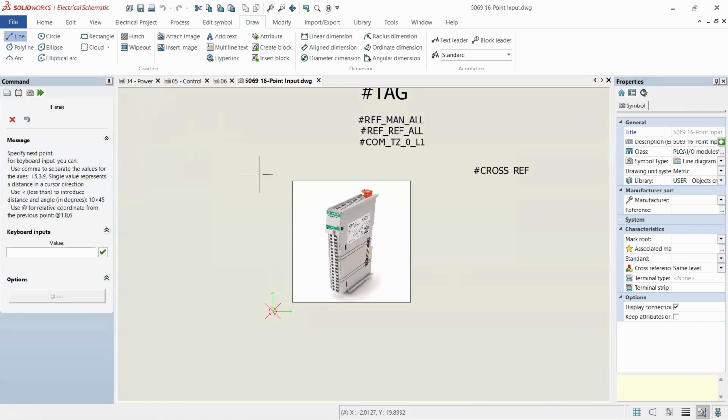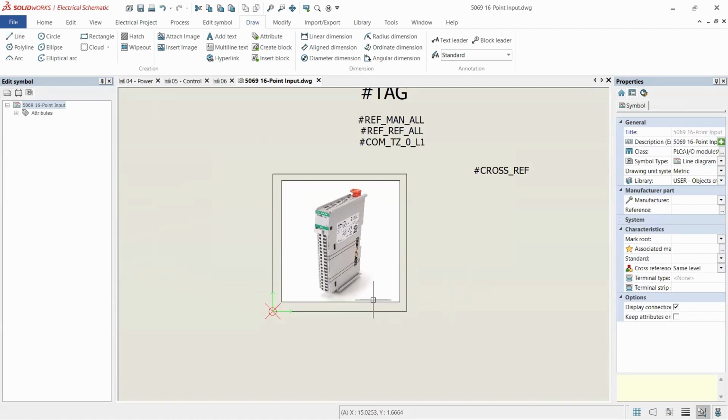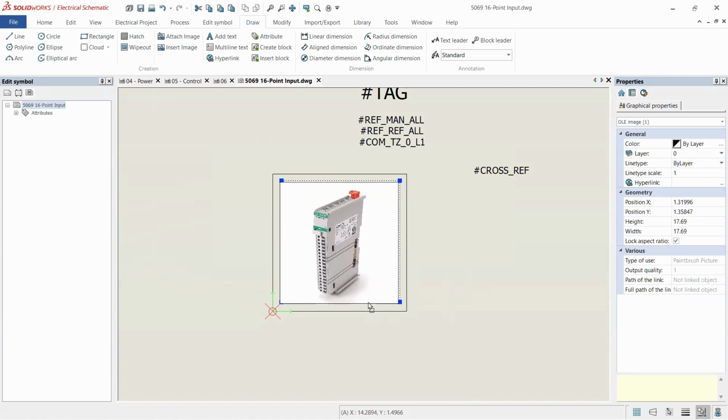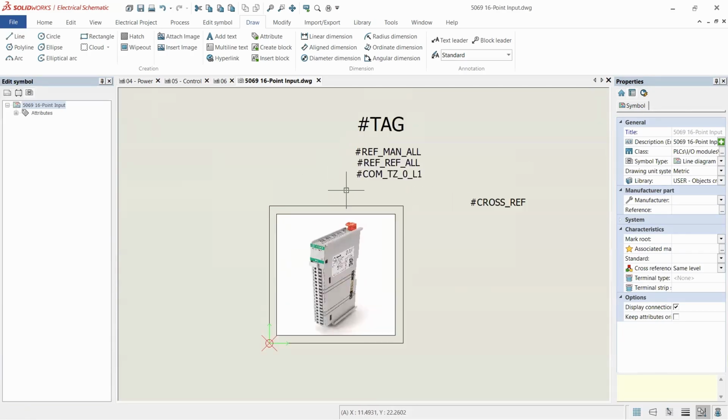So from here, I'm going to go over 10. Oop, I needed 20. Easy fix, another 10, 0, and then come back down at 0 comma minus 20. And then now I can do an absolute, go back to the origin 0,0 because it's closing the box. Move the picture sort of in the middle of that. It's handy because it was a square picture. I think it said 1,000 by 1,000 pixels. So there, now we've got an image in. Now we can sort of build.